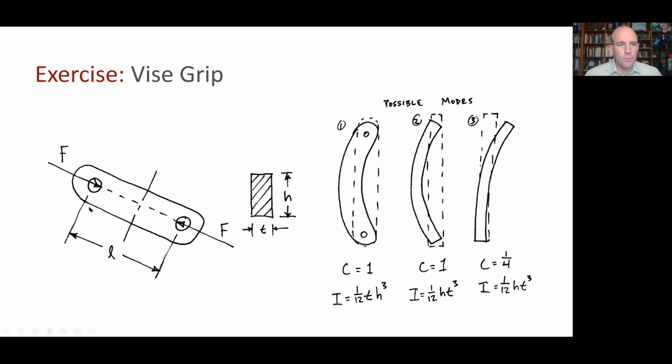And we're going to have to define this length. We know that'll show up in our buckling equations. And we'll have to define something about the cross section. Let's say it's rectangular with a thickness and height. And then we get to the big tough decision, which is what is the mode of buckling that we're most concerned about and therefore that we model.